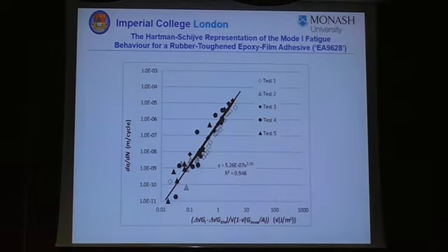So I've now replotted it with the Hartmann-Schreiber idea. Threshold, G1C basically. This is the Hartmann-Schreiber plot. Notice that all the tests really collapse rather nicely onto one straight line. Coefficient of variation is 0.95, so it's quite nice. The slope is 2.55, so it's not like the 9, 10, 20s you see when you use the alternative methods. So it's a very nice plot.